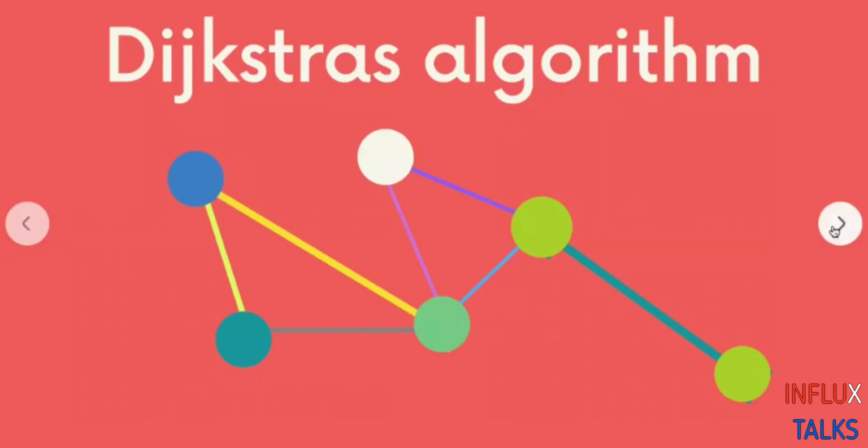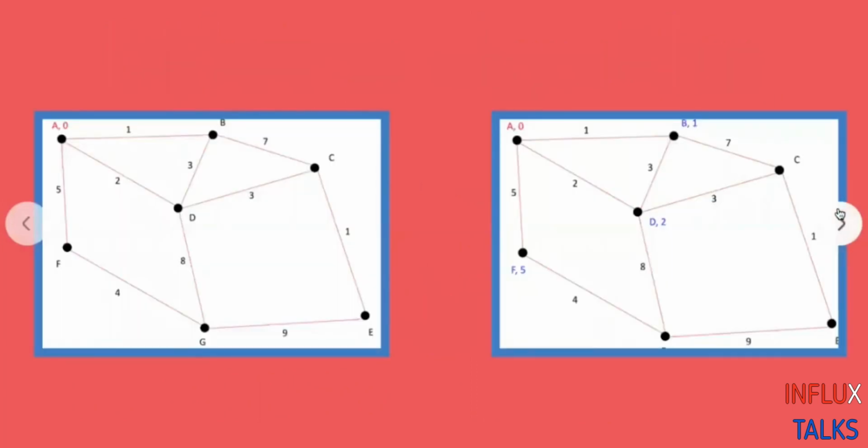The next algorithm is Dijkstra's algorithm, which is easily the most popular algorithm for path planning out there. In Dijkstra's algorithm, we consider a slightly different kind of grid, because Dijkstra also works with costs or distances that are not implicitly or explicitly 1. We can give different distances and different costs to each of the edges. Here we can see A, B, C, D are the vertices, and the red lines are the edges, and each of them comes with a value that's marked right above the edge.